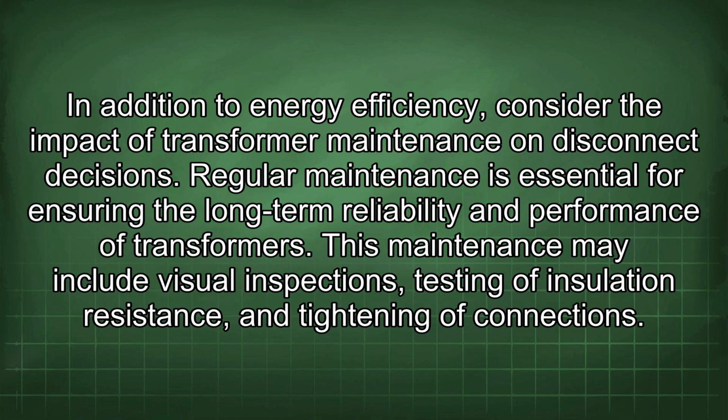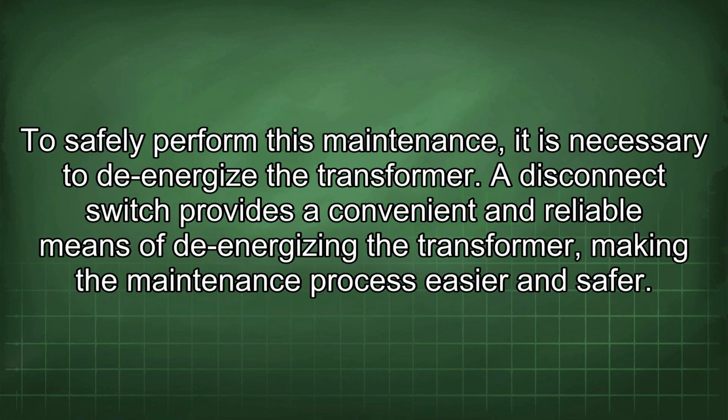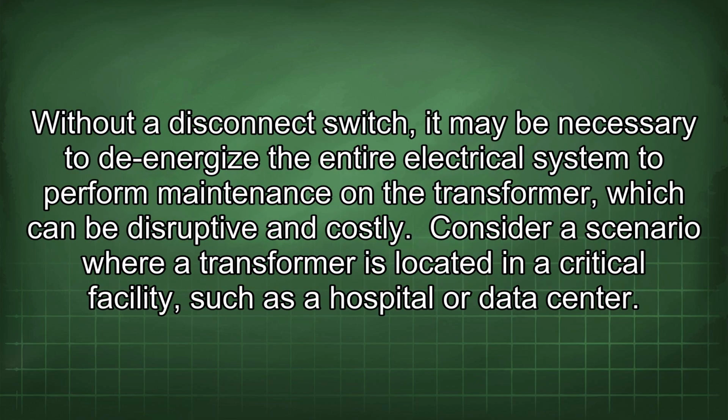Regular maintenance is essential for ensuring the long-term reliability and performance of transformers. This maintenance may include visual inspections, testing of insulation resistance, and tightening of connections. To safely perform this maintenance, it is necessary to de-energize the transformer. A disconnect switch provides a convenient and reliable means of de-energizing the transformer, making the maintenance process easier and safer. Without a disconnect switch, it may be necessary to de-energize the entire electrical system to perform maintenance on the transformer, which can be disruptive and costly.